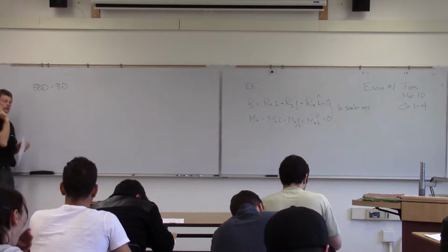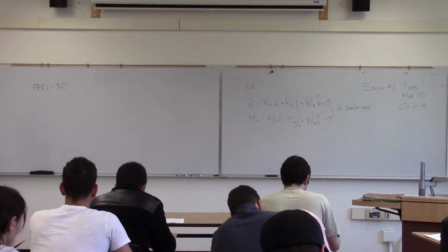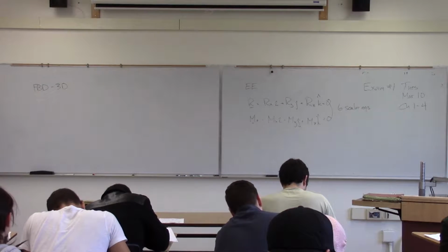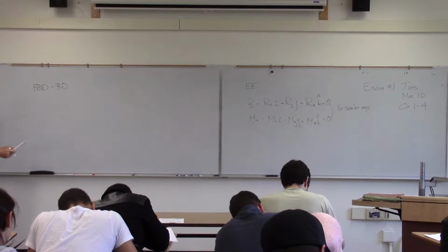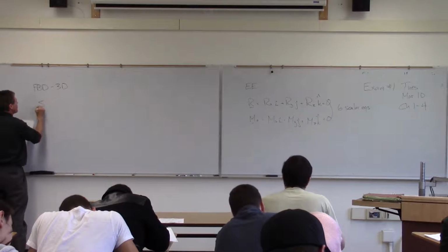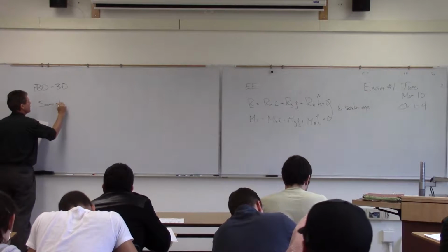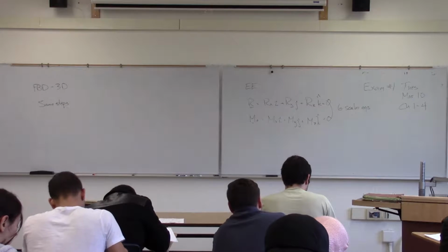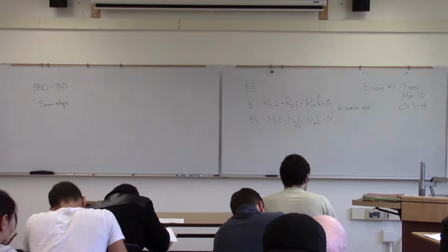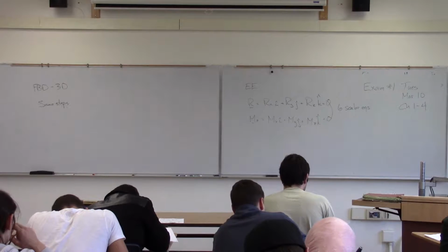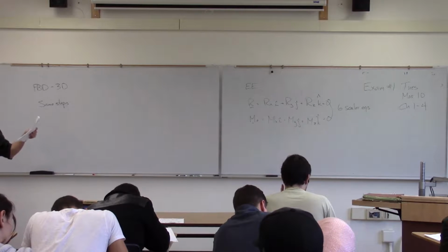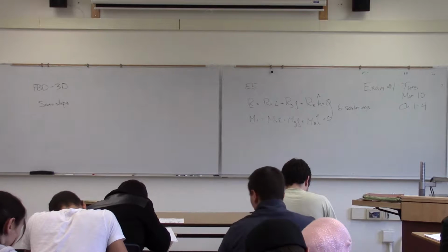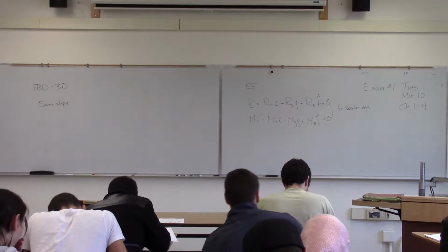And again, I'll repeat it, if you don't draw a free body diagram, you will lose points. So when we're doing an equilibrium problem, if you don't have a free body diagram, I have no idea where your equations came from. I won't repeat them, but it's basically those same steps. Pick an outline, again, an outline. So we're not looking at what's going on inside. Remember we talked about that when we looked at that piece the other day with a hinge in the middle. Where are the forces of that hinge? Well, if that's part of the free body diagram, then it's internal to that. We don't show those forces until we pull it apart at that hinge.